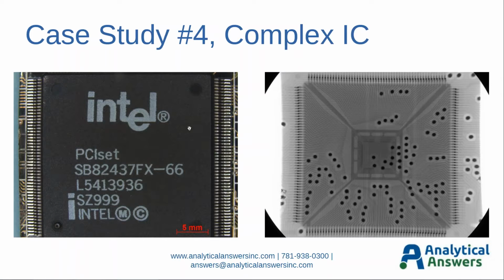It's always recommended that we optically document any sample before doing any failure analysis. So we want to do a proper non-destructive documentation of the sample, whether it be an integrated circuit package, an MLCC, even a printed circuit board. We want to look at the exterior and optically document that in a non-destructive manner before we go ahead and do any sample preparation, cross-section sample preparation to that, excuse me.